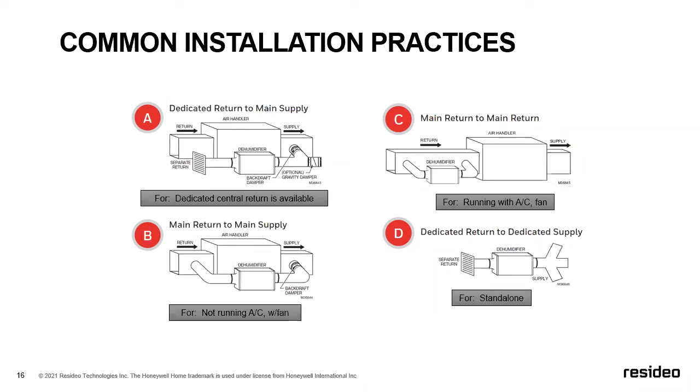We just got to know that we're going to be dumping some hot, dehumidified air on that evaporator, adding a little bit of sensible load, but probably nothing that the air handling unit HVAC system can't handle. You guys out there that are contractors, I always kind of put back on the contractor, just understand the little load. Is that an issue for you? If it is, then we'll lock it out on a call for temperature. But we also know when we're setting up the controller that we're just going to tell it, hey, we want the air handling unit fan to run when the dehumidifier is running. And that's a simple configuration selection when we're setting it up.